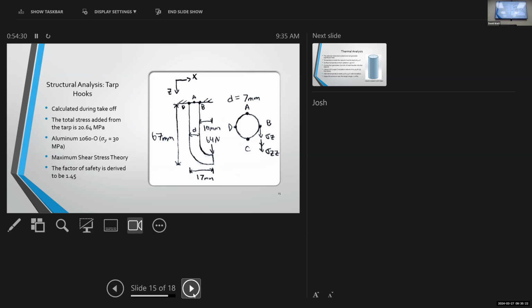First, I don't know what the difference is between sigma z and sigma zz. Second, the direction of sigma z is wrong. If you consider that is the x direction, z is the downward direction, and then your a should be the positive y direction, and your sigma z direction is wrong. Yeah, the direction is wrong. And also you mentioned that first you used 7075-T6 as the structure, and then because your safety factor calculated is higher than 1.5, you changed to 1000 series.